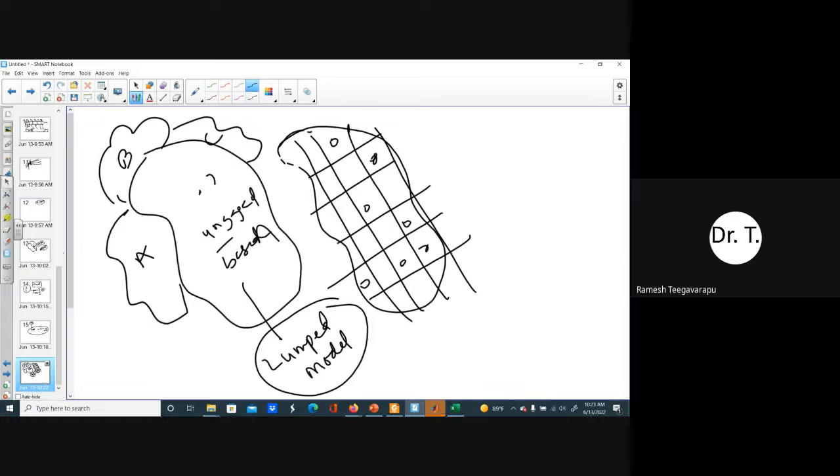So definitely, if you are lucky to have some rain gauges, and if you are able to get either IMD products or radar based products, this is much better for distributed modeling applications. Whereas in the lumped model, you cannot apply distributed hydrologic modeling because there's no way you can generate those gridded precipitation data.